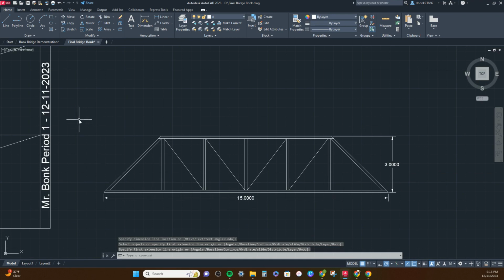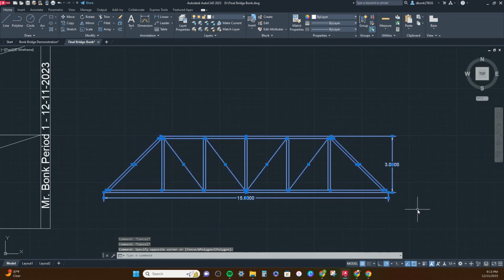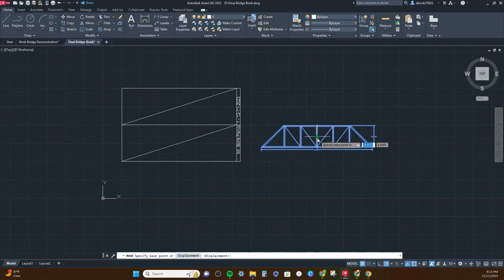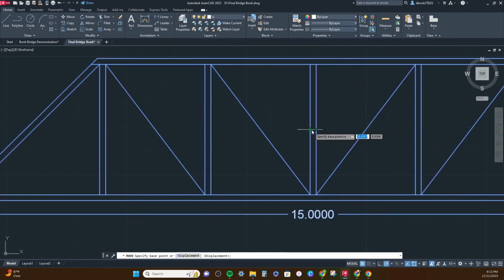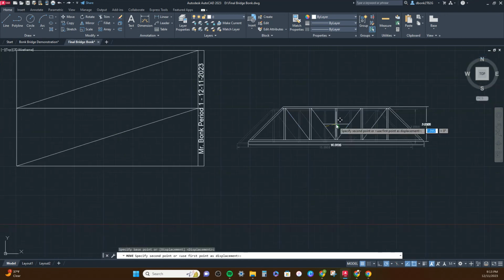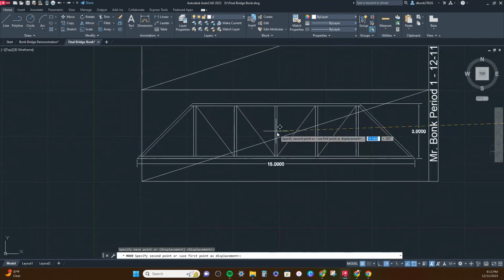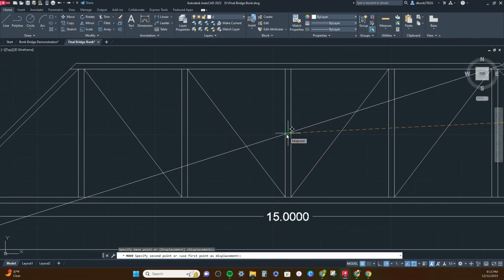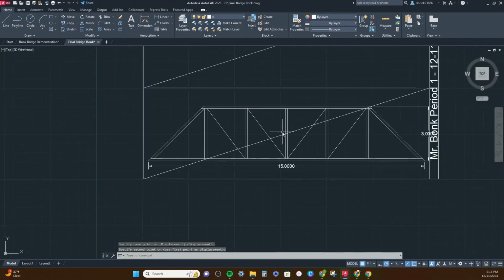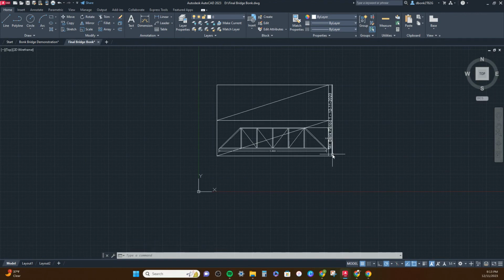All right, watch this. I'm going to hit escape, make sure nothing is on. I'm going to click on this side, let go, click over on the other side to select everything, go to move, and I'll go over. That's actually going to grab, if you see the X in the center there, that's going to grab this thing by its geometric center. What you want to do is mouse over the triangle. It takes a second to get it where you want it. Mouse over the triangle at the midpoint of the diagonal behind it to place that ridge wall.